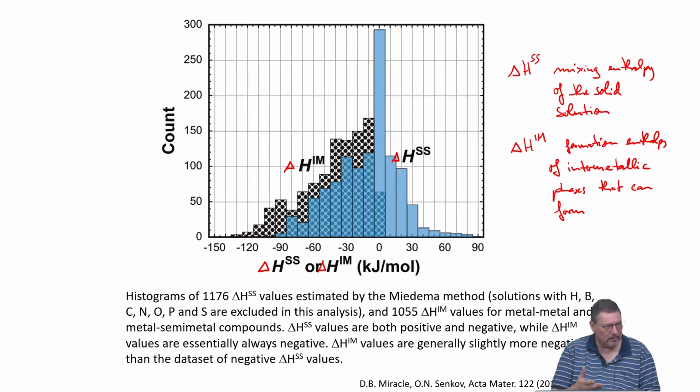Your friend can be that the time for forming these intermetallic phases at the lower temperatures might be very long, because the diffusion coefficients of the elements inside of these materials is very low, and you need diffusion, you need atomic mobility for the phase formation to occur. So it means the comparison with these predictions is a little bit difficult, because you never know ahead of time how long it takes.